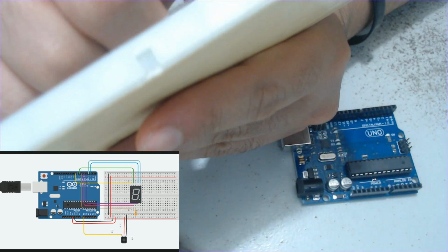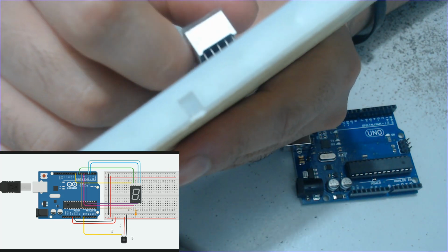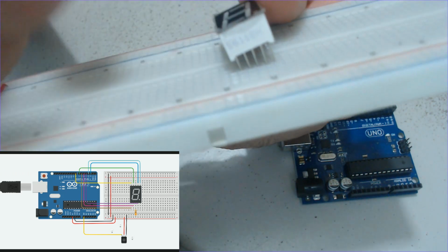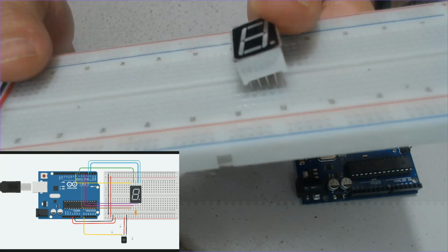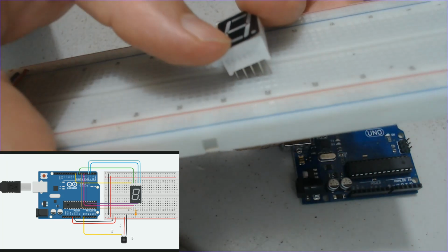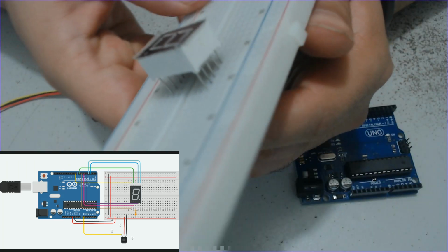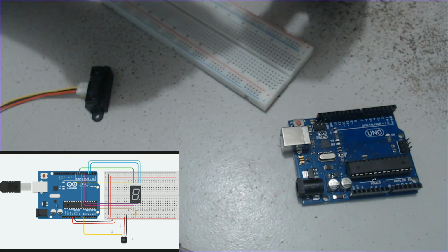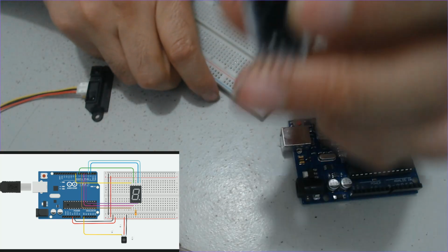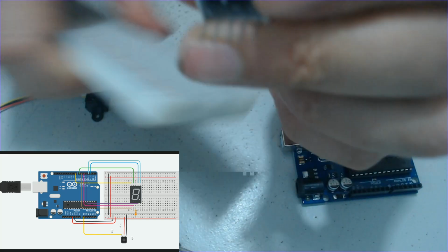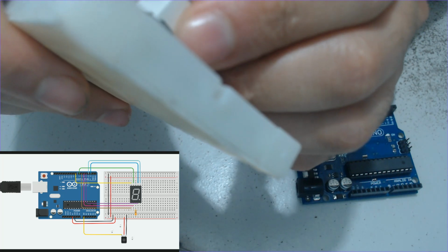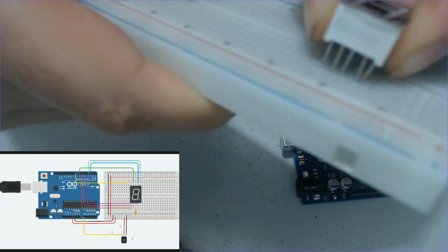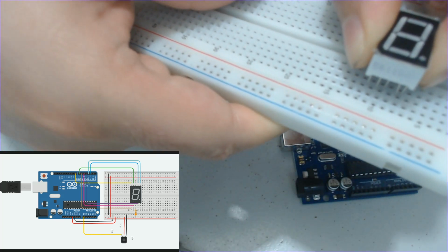Be careful, please. Be careful, check that all the connection ports enter only to a single hole in the breadboard on the two sides of the breadboard, because sometimes you may not be careful. You may have something like this, two legs together, and then you push these two legs, you see, into a single connection port.